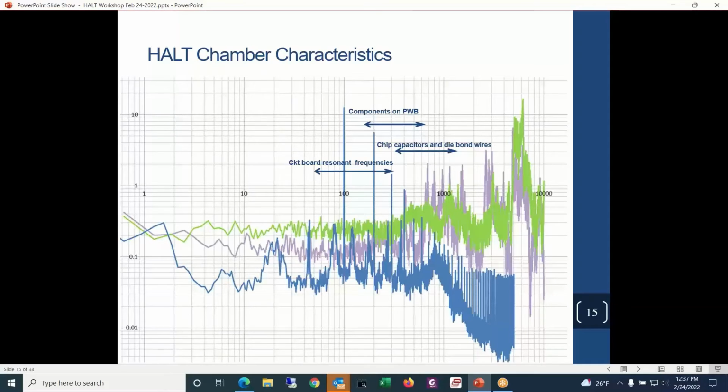They're smaller structures. So the effectiveness of the vibration you apply depends really on its character. HALT does produce vibration over a pretty wide range, but you can see that it's in these higher frequencies that the HALT vibration is a little bit more active.